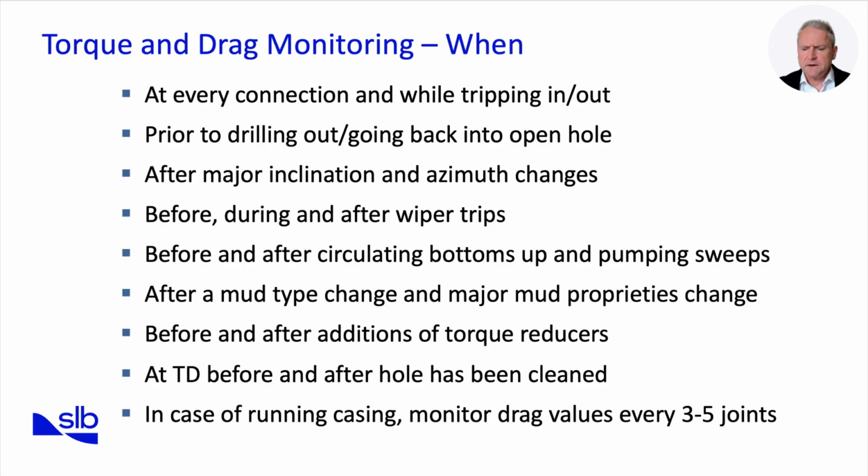Monitoring is also essential prior to drilling out or re-entering open hole, particularly after casing or a sidetrack. This ensures any drag increase is detected before significant progress is made. Other key checkpoints include after major inclination or azimuth changes, where side forces increase and drag behavior shifts. Wiper trips designed to clean the hole should always be bracketed by measurements to confirm their effectiveness.